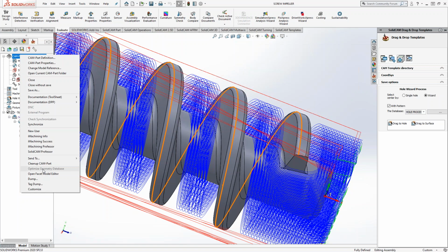Yeah, it's a good point, because going from older files to newer files, this is something that was introduced, I can't remember if it was the previous version or the one before it, but it's exactly like Kevin describes. All those geometry tags, all that geometry that's being referenced throughout the toolpaths, throughout the file itself, is sometimes the thing that can really slow it down, where nothing's in order. Basically what this is doing is reducing the look-up. It's almost like the defrag on your computer.